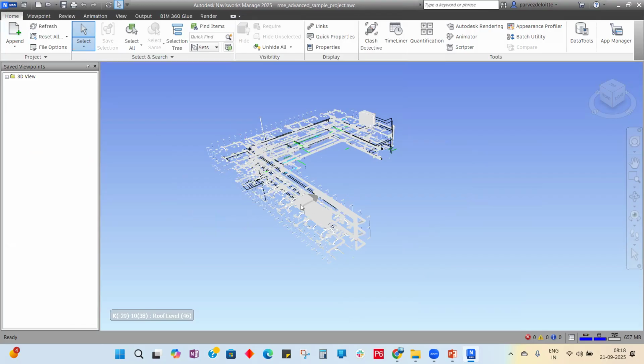See, there was a structural file which was here. Okay. So what I had to do is go there and then append the file in that structural file. But here, what did I do? Without appending the file, I opened the other discipline file. So what will happen in Navisworks? If you open any new file, the previous file will disappear.